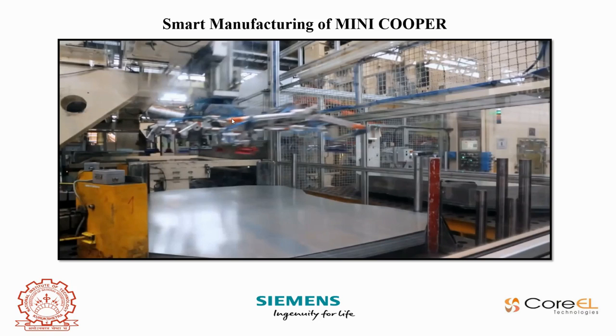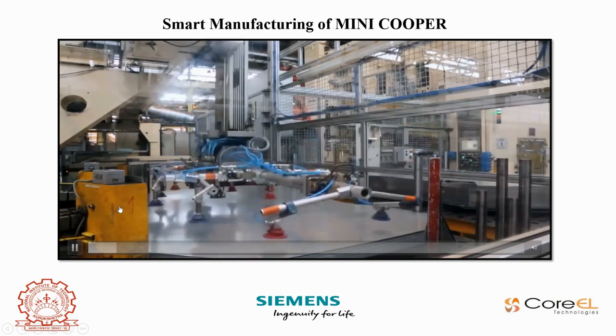What is its motion here? Picking, sir. Linear. Okay, so the application is picking, but the type of motion the robot is performing is linear only. It is picking a part, going somewhere and placing it there. That is what I am saying: based upon the end application, we are going to define the robot. This application can be done by an articulated robot also, but it depends on how much it will rotate. If it is a linear application, based upon the size, it will be like this. Based upon this only, the robot will be classified.